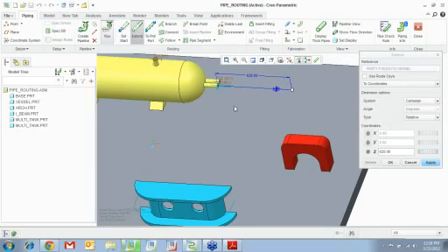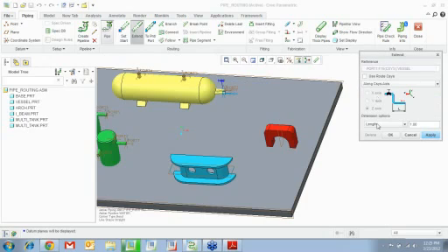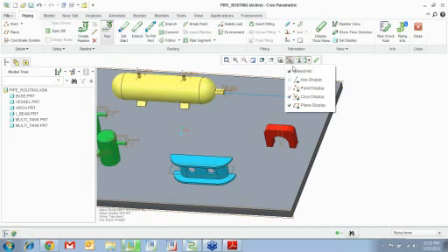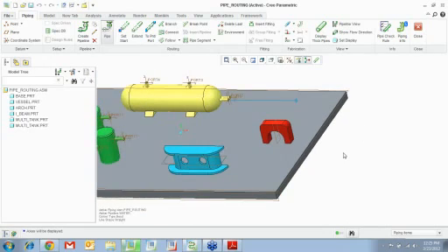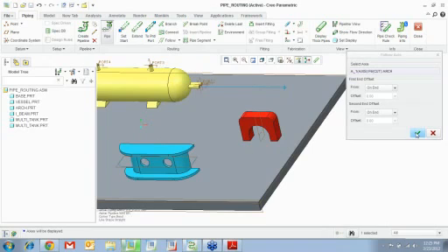So when you extend, you can enter a value and you can drag it, or you can also go along an axis, see that? X, Y, or Z. You can go offset from references. So pick this. I'm offsetting from that reference to 0, so it's going to stop right there. I say OK. Now what you can also do, I'm trying to use one example to show you every possible way of doing it. Okay, so you can say follow an axis. I'm going to pick the axis. So notice you can start from the end and end till the end.